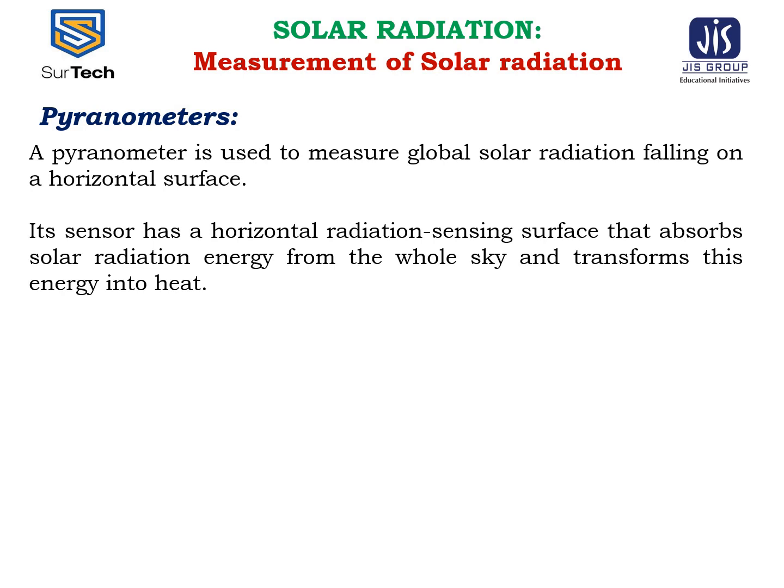In practice, they are designed and manufactured with great expertise. The basic measurement is total irradiance on a horizontal surface, G_TH. Other measurements can be of diffuse radiation only, with direct radiation prevented by an adjustable shade ring, or of beam radiation G_B* only that enters a collimating tube continuously tracking the sun's path.